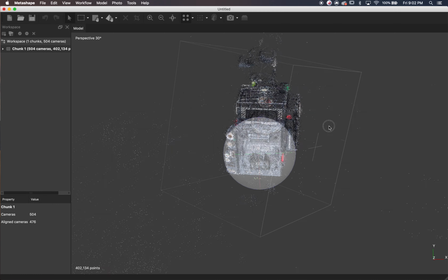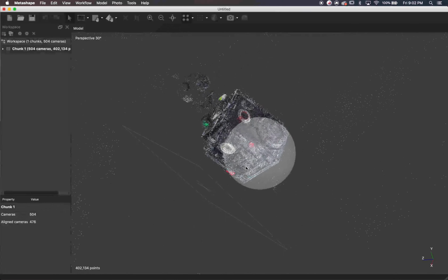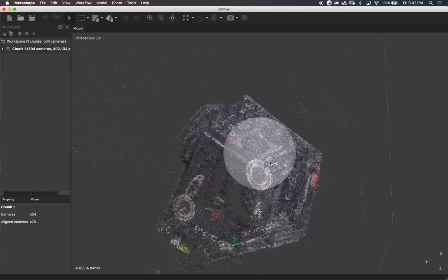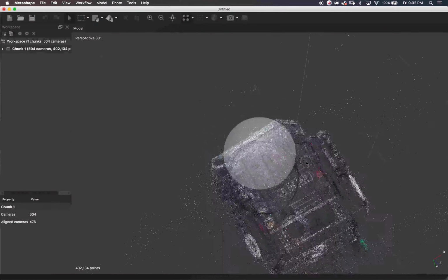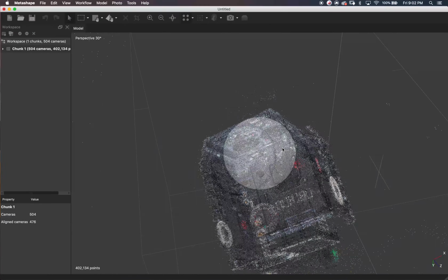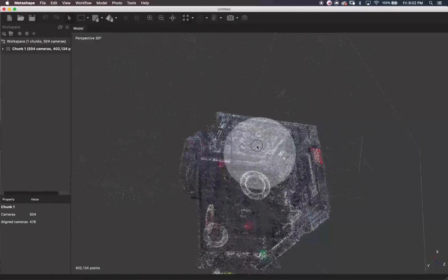So when aligning the photos, the first thing it does is build what's called a sparse point cloud. These are just features that the program found in each image that it thought went where it put them. And it built this really basic geometry of this object. Just tooling around here, I can see all of these dots all around my object, right? And that's the noise that I was talking about. It's the sky, it's the driveway. I don't want any of that stuff.